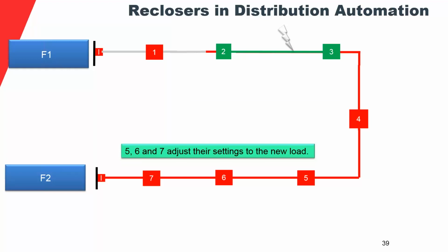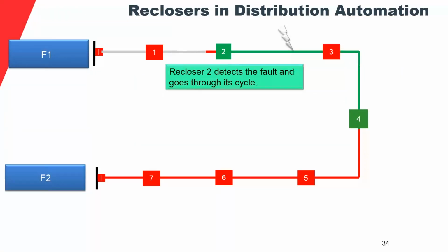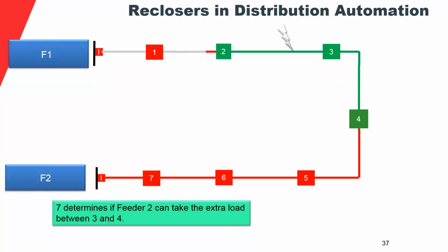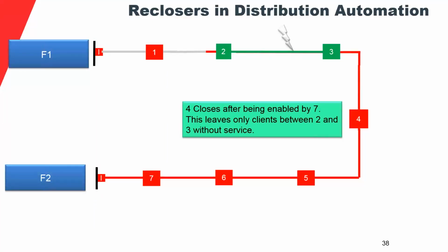And remember, here I didn't say which protocol was being used to propagate the information between the relays. It could be a proprietary protocol, or it could be something as advanced as 61850. Also, I didn't talk about the medium. You could have radios between all of the reclosers. You could have radios on one side and fiber optic on the other. This has nothing to do with the protocol or the medium used for the communication. It can be implemented in many different ways, being such a simple but yet, in my opinion, powerful idea.